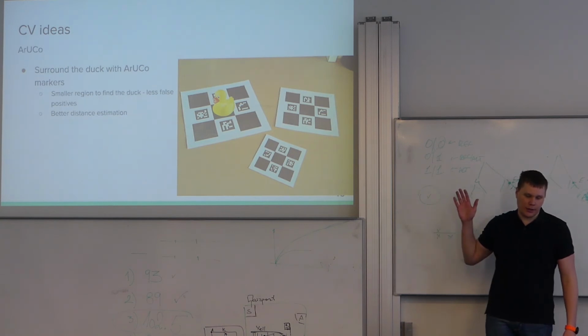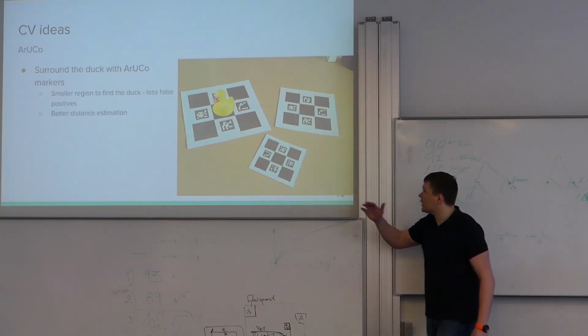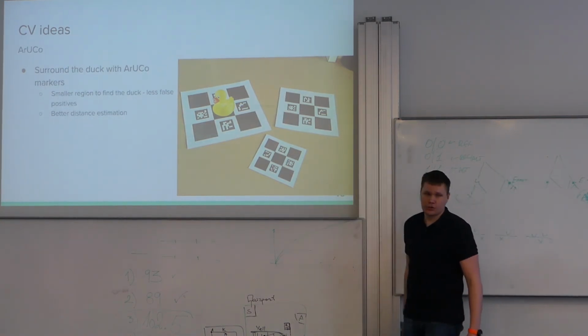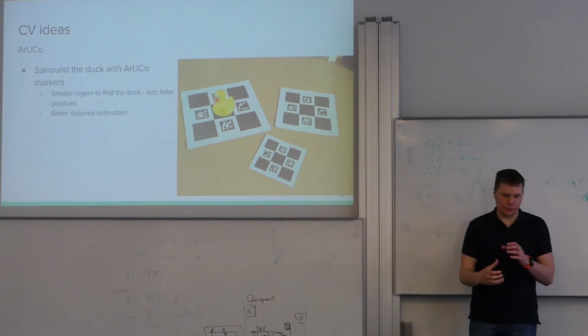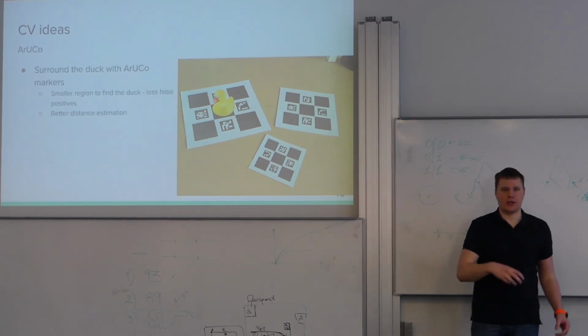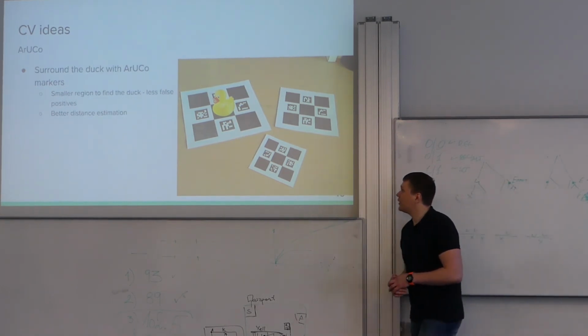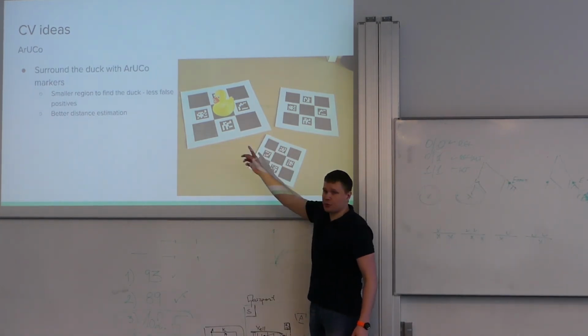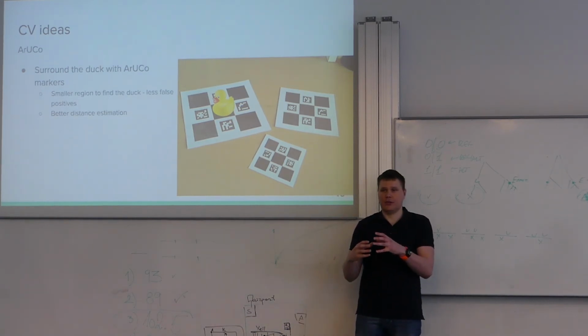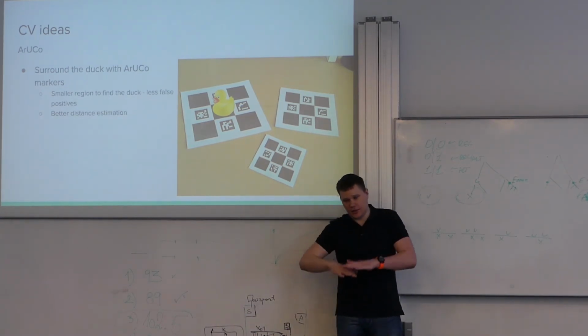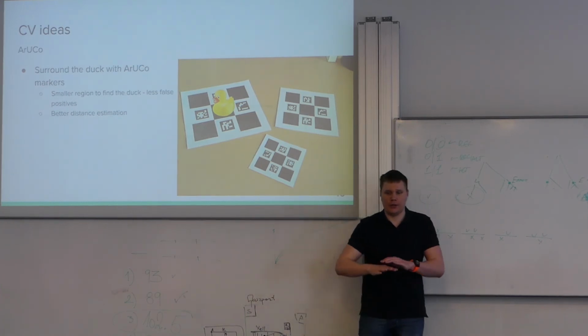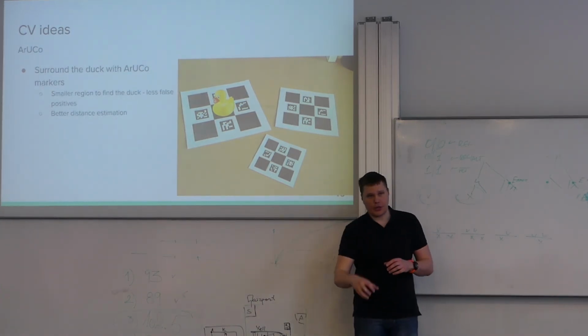Another idea, you can take special structures, like we can have a lot of ArUco markers and place our duct inside them. So surround our duct with ArUco markers. It gives us the exact region where to detect the duct, and it gives us exactly how far we are from the surface where the duct stands.